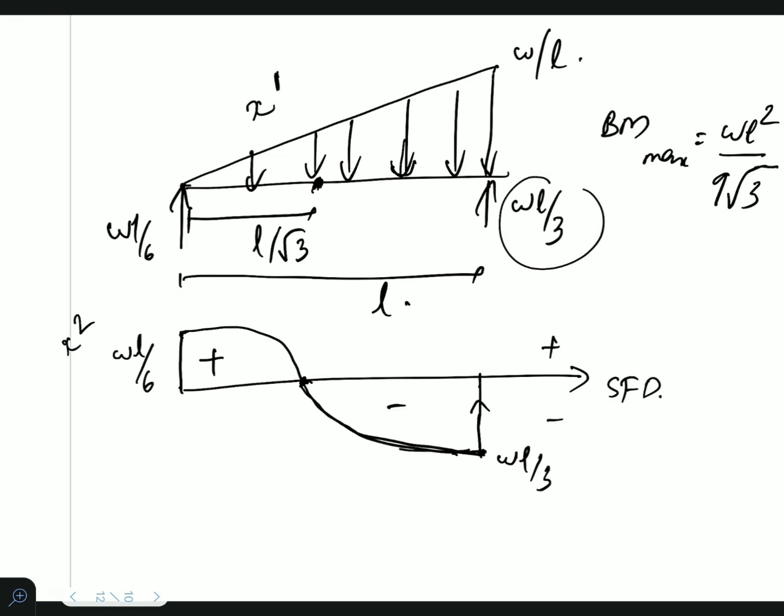Okay, so that is the bending moment diagram now. See, this is a sagging case, so the bending moment diagram is always positive. We represent it upside. So here we have 0 value and here we have 0 value, and we will have a maximum value at this point, which is a distance of L by root 3 from this A point.